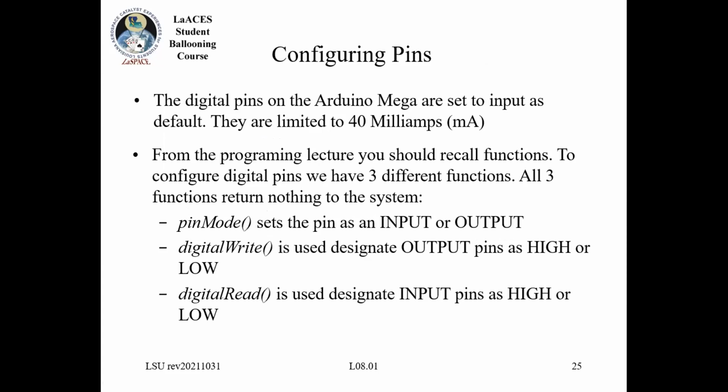And what this is saying, that they are set to input by default, means you can read the pins by default, but you can't write to the pins by default. Now, in the programming, you use this pinMode function to tell it whether you want the pin to be an input or output.